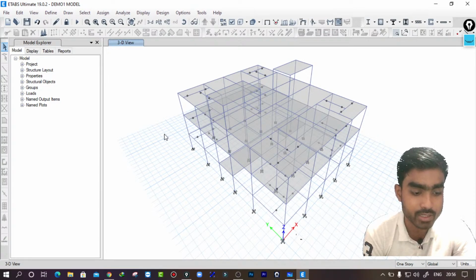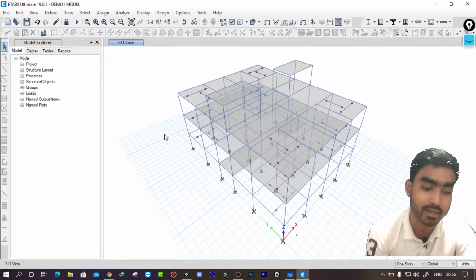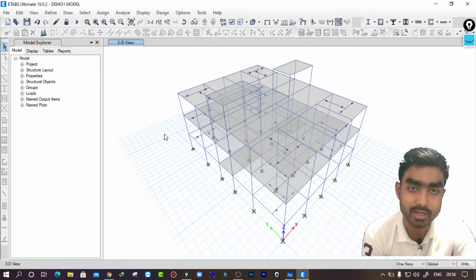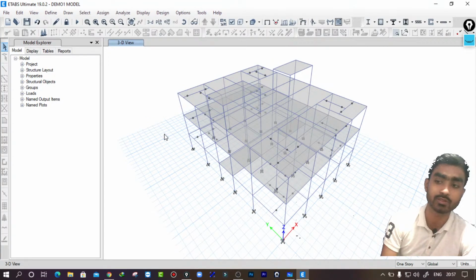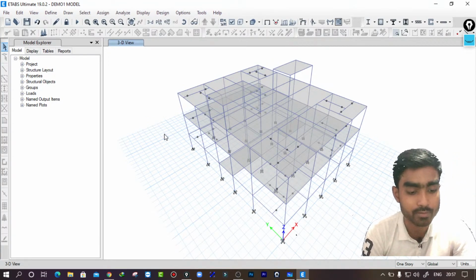Is there any more question? Yeah, Mahesh, what I'm saying is there are different checks: stability checks and irregularity checks. Then the modal check is a very important check. If your modes are not correct and you go with the dynamic analysis, you will get very wrong values, because the response spectrum totally depends on the mode shapes. It makes the combination taking the mode shapes itself.